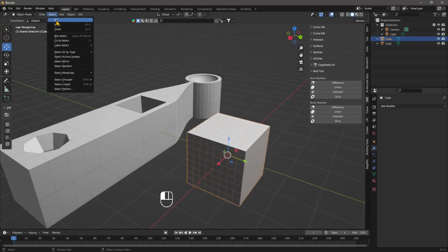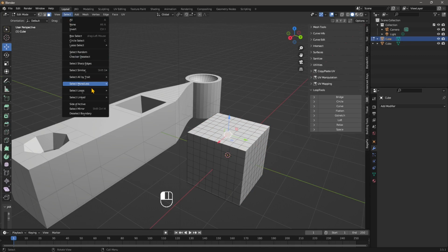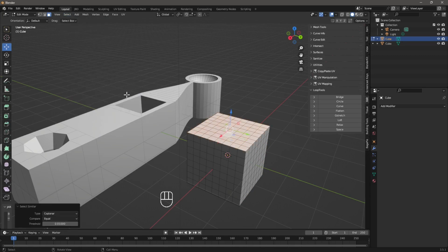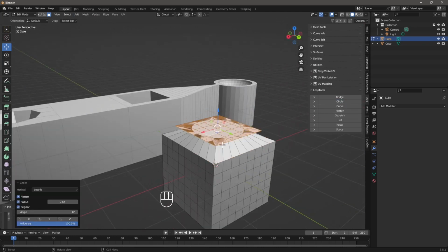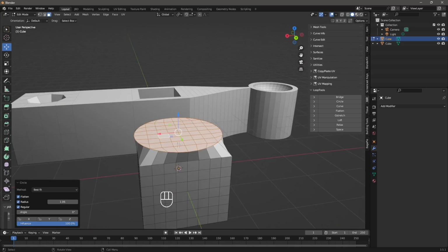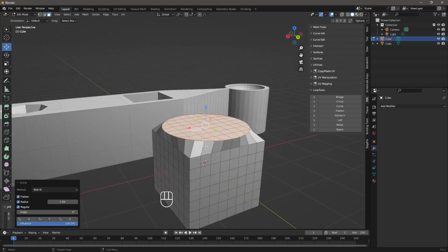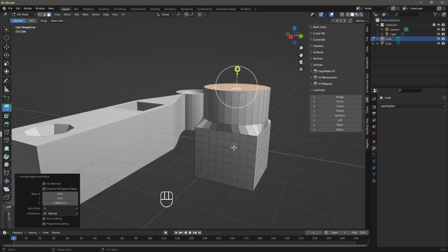And by the way, let's also check here, well, I want to go to edit mode first. And I want to select one of these and select now the similar, and I'm going to go to coplanar. So I'm going to select all these faces that are in the same plane, and let's do circle. So you can see now it looks strange, so we may want to adjust the radius, but you can see it's kind of doing a loft between this square and this new circle, and it's looking more like a circle because we have more subdivisions. And then I can extrude this, I can continue with this and move on. I can create like a column or whatever.